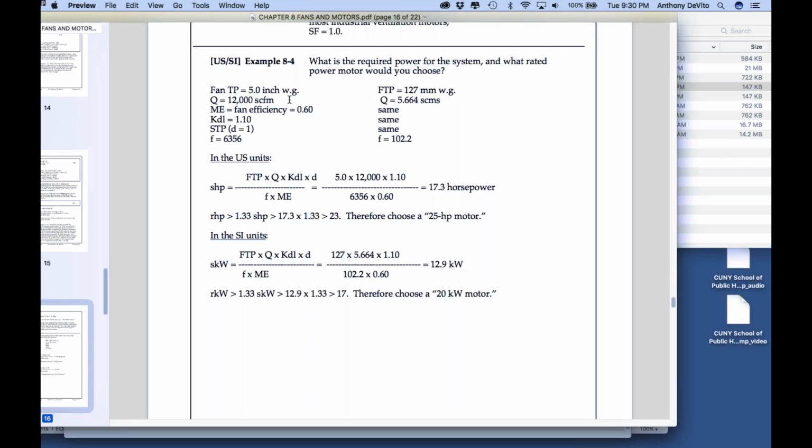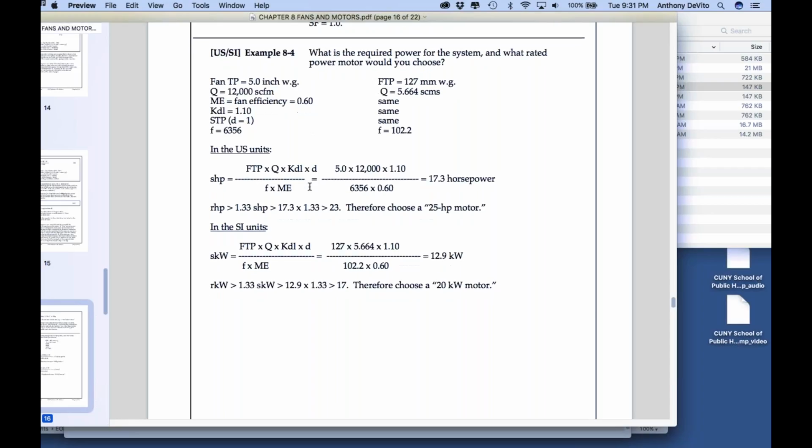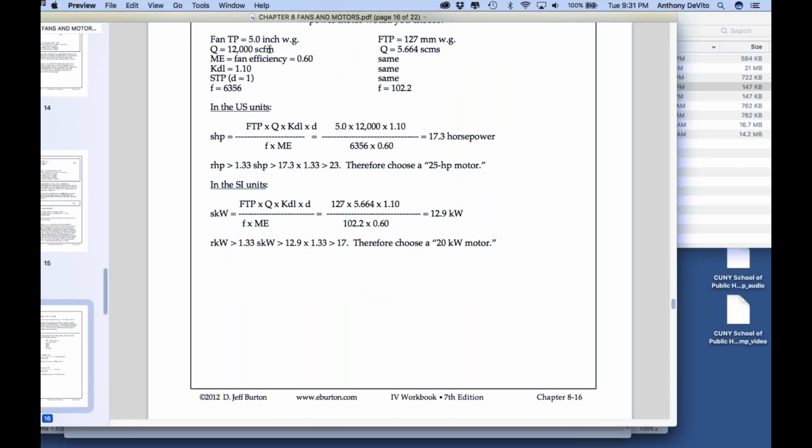But if you have to duct it, then you have to figure, I'm connecting an 18-inch duct, 20 feet of it going out here, an elbow, 100 feet of it to go up to the roof, right? So you're calculating just like you did the suction side. You're calculating how much static pressure you need to overcome the 20 feet here and 100 feet here and the elbow, right? But it's a positive number now, right? Okay. So you can calculate that.